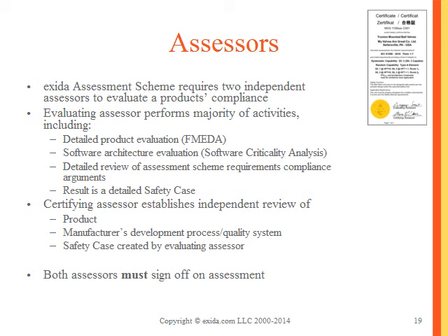The result of all that is what we call a safety case, and in our case, we document that in a database where we have all the requirements. We document all the arguments why requirements are met, and then we also embed the evidence documents that support the arguments in that safety case, and that is then the solid documentation why a product meets the requirements of IEC 61508.